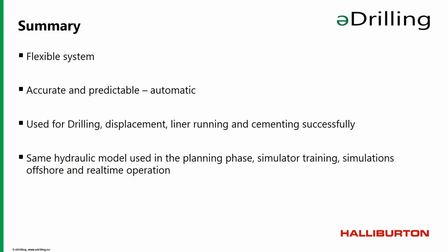And also, like the next question here, does the model take into account cuttings? Yes, as you are drilling, the model takes account of cuttings. It also builds up a cuttings profile, so you can have a good visualization of where your cuttings should be. And if you go back to what I talked about, taking a state from the well, then all your cuttings concentration also follows the state, so you can have it with you.